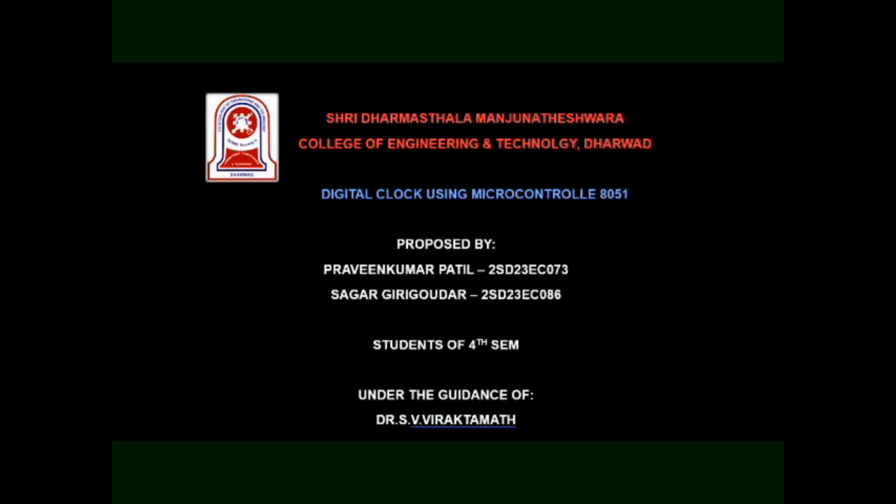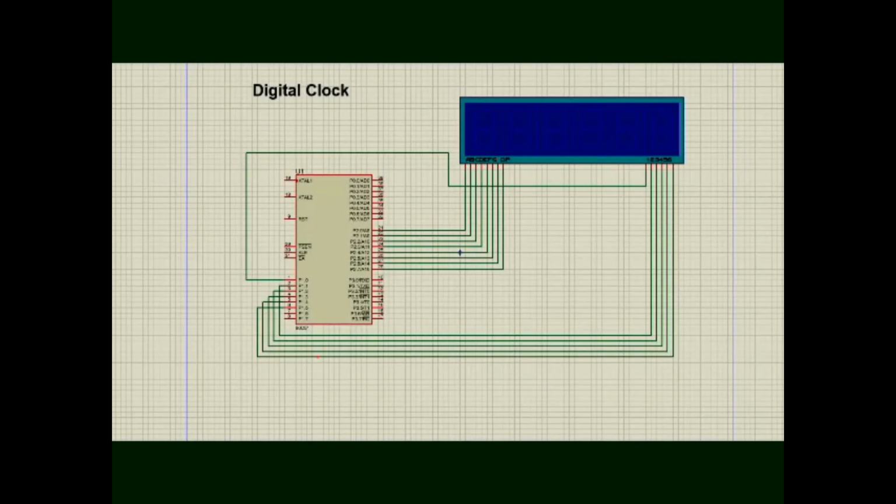Hello everyone, I am Praveen Kumar with my ally Sagar. We are explaining the working of a digital clock using 8051 microcontroller. This is a simple digital clock circuit using 8051 microcontroller and a 7 segment display. At the heart of the design is the 8051 microcontroller which controls the entire clock logic. It is connected to an 8-digit 7 segment display that shows the time in hours, minutes and seconds.